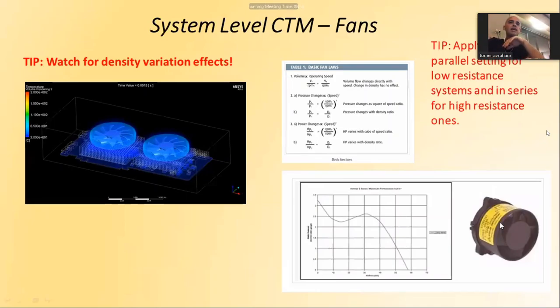This fan is a vane axial fan. It's a fan that is more for high pressure and average CFM, average volume flow rate. Your computer at home has a tube axial fan, which works against low pressure and supplies a lot of air. There are many demands for a fan besides the point of operation. This fan here is called Rotron Aximax 2.